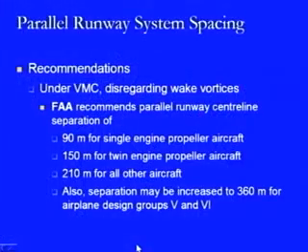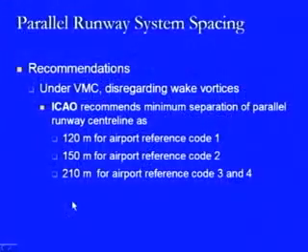The recommendations here are that under VMC, with respect to the wake vortices, the FAA recommends a centerline separation of 90 meters for single engine propeller aircraft, 150 meters for twin engine propeller aircraft, 210 meters for all other aircraft, and a separation increase by 360 meters for airplane design group 5th and 6th category, that is the bigger category. Further recommendations are that under VMC, we should disregard the wake vortices.